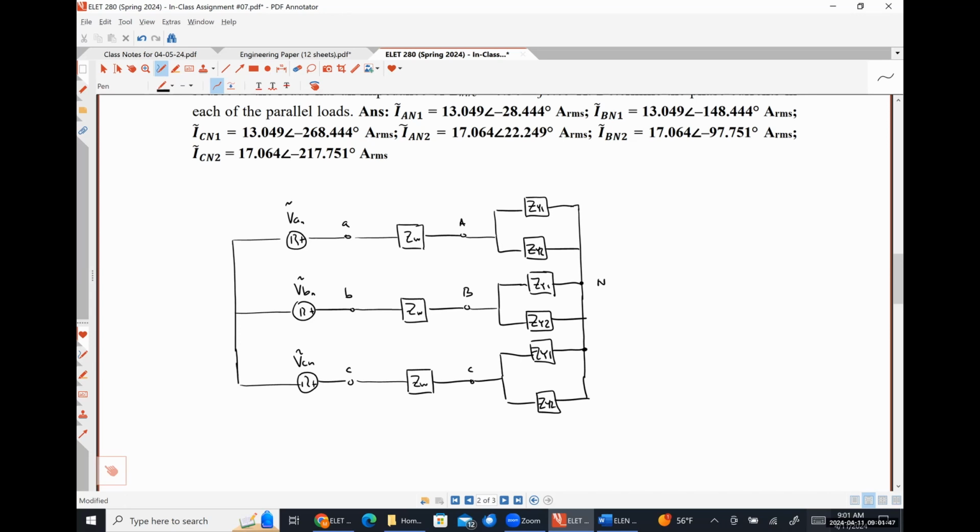Or because all of these circuits along this wall are probably literally wired in parallel to the same breaker, if I plug something into this receptacle and then one into one of the receptacles down there, as long as it's a 120 thing, it's the exact same thing. Our voltage source would be in our breaker panel. Our transmission lines would be the wires that are connecting our breaker panel to these receptacles, where these receptacles are pretty much just the terminals that we are connecting our loads to. It's just that exact same thing, but with a three-phase system.